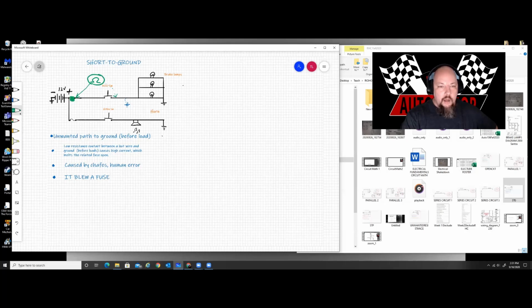So I'm going to feel confident about coming here to my light connector, disconnect my light connector. Then I'm going to go ahead and probe again. So, well, I still have got that connection to ground over here.